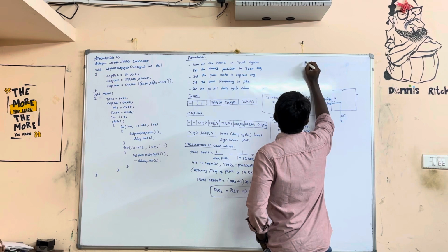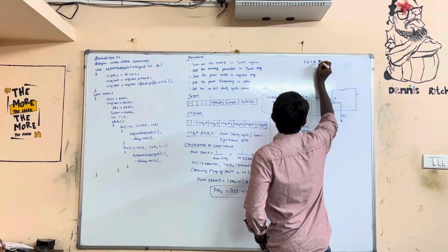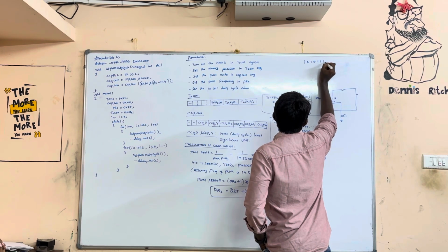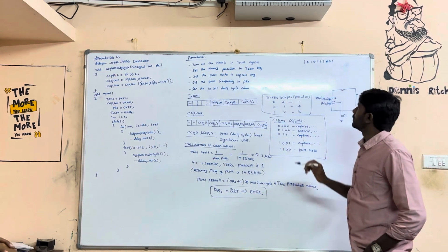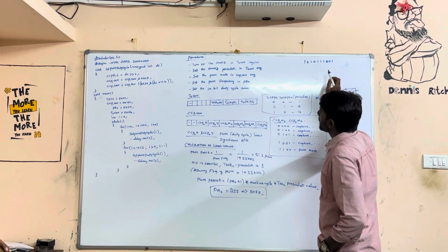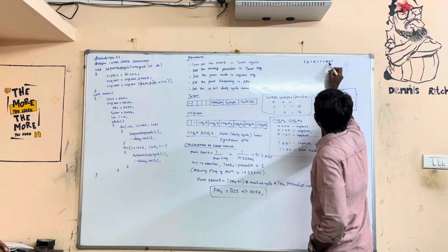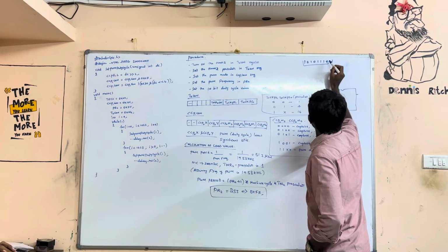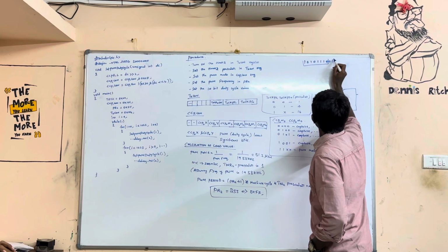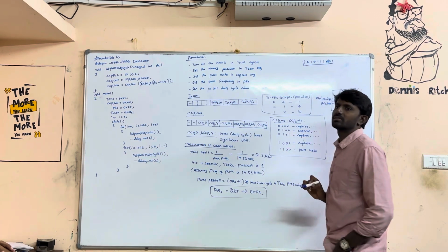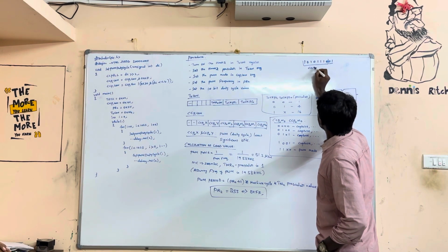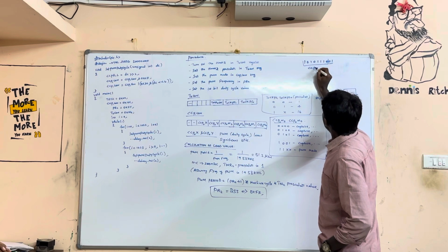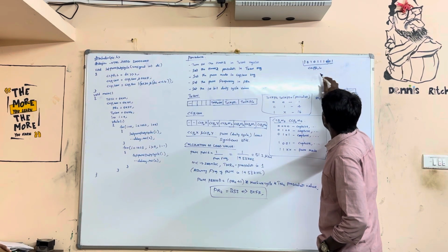Let's take, this is your 10-bit value. Here what will happen is, these 8 bits will go into one register and these 2 bits will go into another register. Got it, right? So this 8 bit will go to CCPR1L.